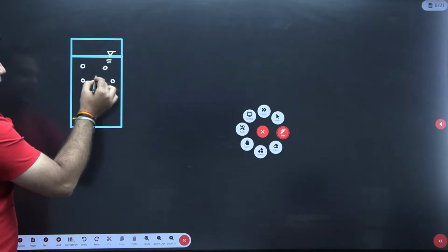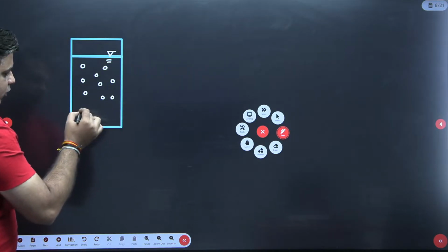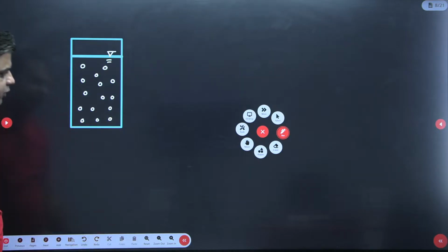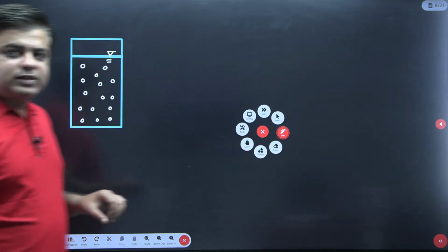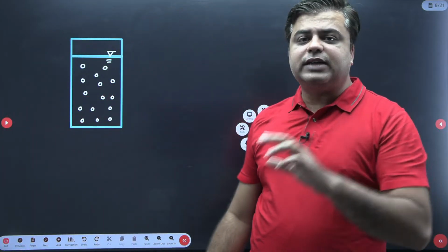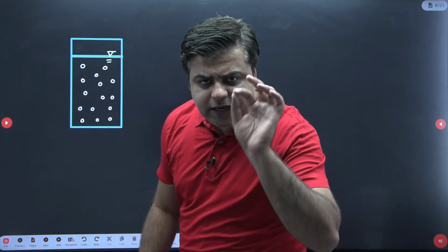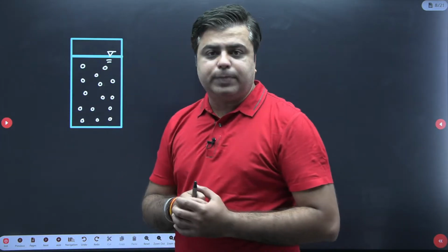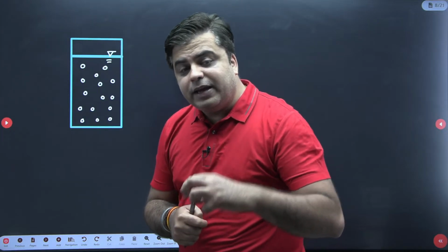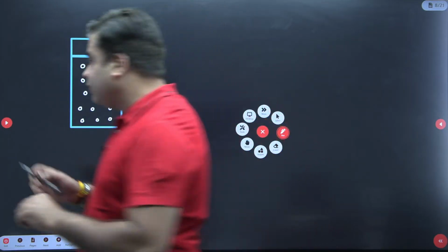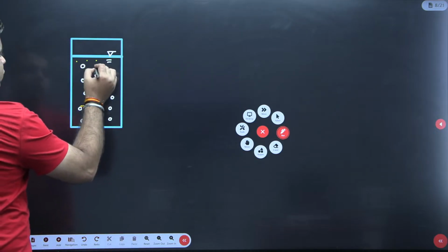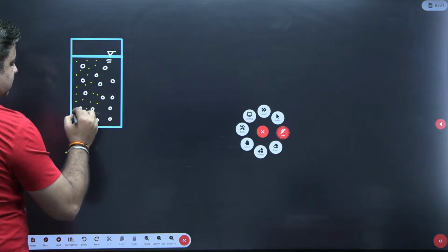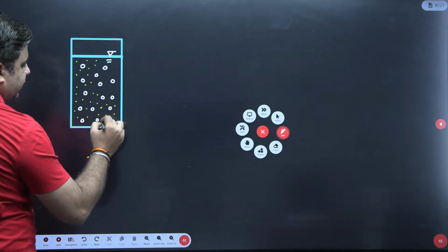Some solids are seen through the naked eyes. So the solids that we can see through the naked eye are classified as suspended solids. We have taken a water sample, and in that water sample few solids are there, and these solids are clearly visible in water. Therefore, these solids are termed as suspended solids. Then there will be other solids which are not visible through our naked eye. Those solids which are not visible through the naked eye are termed as dissolved solids or TDS.